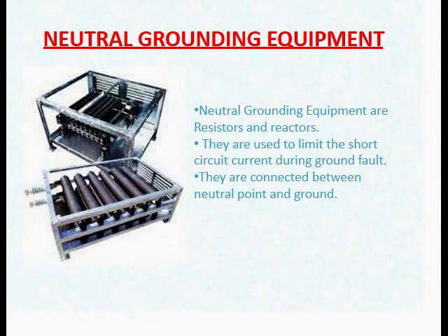Neutral grounding equipment are resistors and reactors. They are used to limit the short circuit current during a ground fault. They are connected between the neutral point and ground.